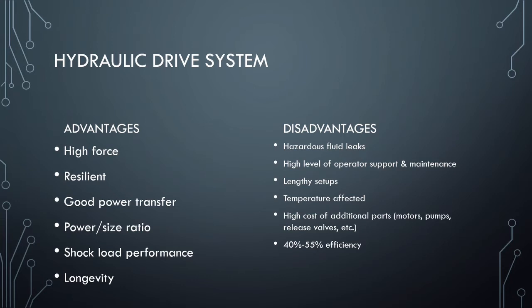I already talked about the shock load. Any sort of shock vibration in the environment, they handle really well, and they can also last a really long time. So they can be a really rugged, durable, high-powered system. Of course, we get to our trade-offs, so our disadvantages. If there is a fluid leak in these systems, it can be really hazardous depending on what that hydraulic fluid is and what the environment is. So they have to be monitored very carefully for leaks.